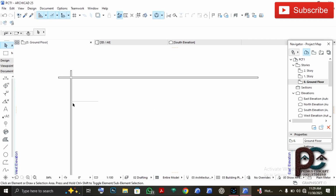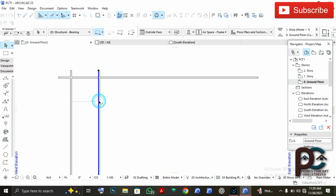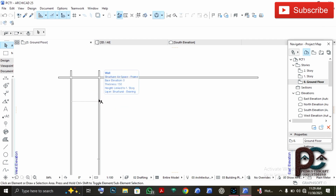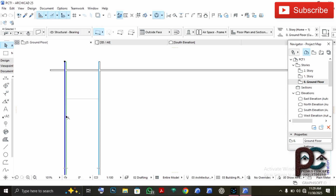We will use lines, and then we'll do Ctrl+Shift+D to make a copy of this. To drag a copy of this, you hold your shift and then keep on that point. But to make work faster, I use my drag tool. Once I click on drag, I'll drag and add an extra 150.